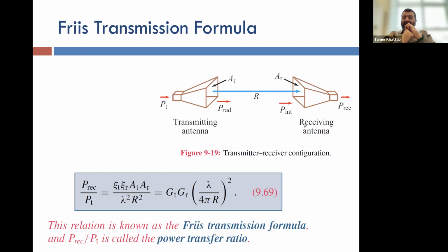Now, what happens when we are dealing with another environment? Let's talk about Wi-Fi inside a building, or cellular signal downtown, on the streets between buildings. Of course, in this case we have lots of reflectors, and the signal is no longer just one path from the transmitter to the receiver. The signal can go through a reflector and arrive here, another reflector and arrive here, and so on. So we have all these possibilities of what they call the multipath effect, right? The signal comes from different directions.